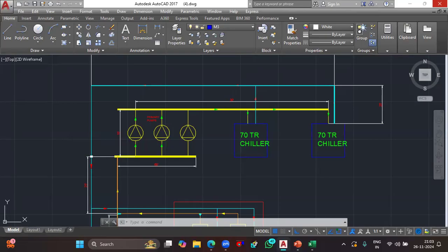In the previous two sessions I explained how to find out the cooling tower concepts. It's very simple. For 1 ton, the equivalent water capacity is around 3 GPM to 4 GPM, so you can directly calculate it according to the chiller. So don't forget that stuff also. Now we are jumping over to the last of our HVAC sessions, the topic which is ventilation.